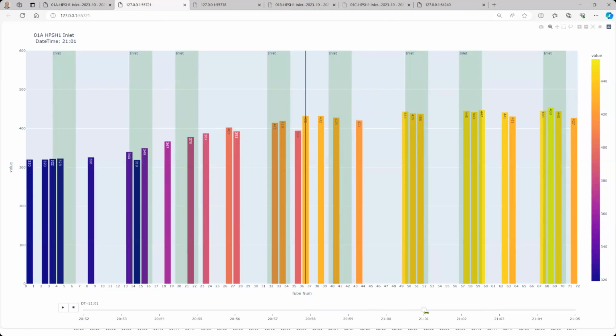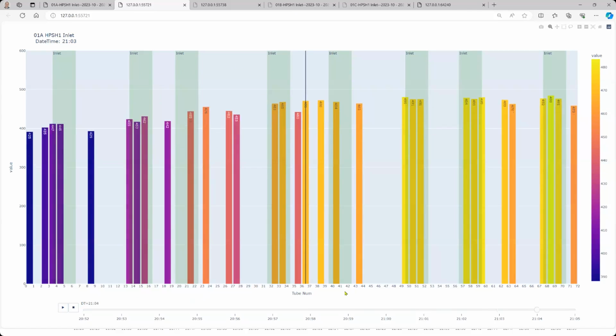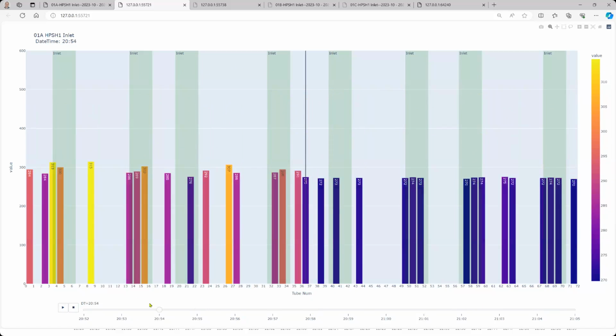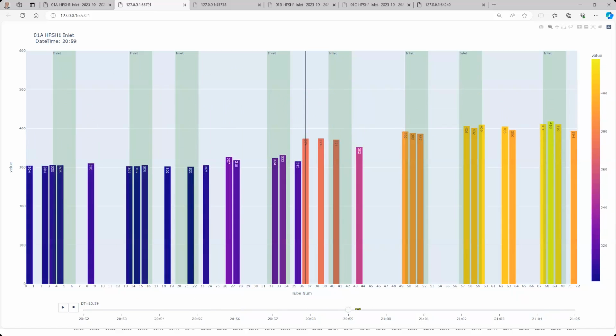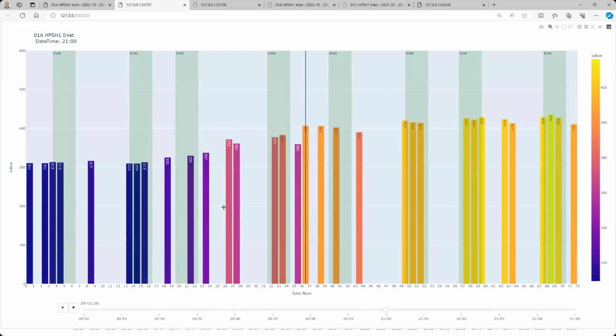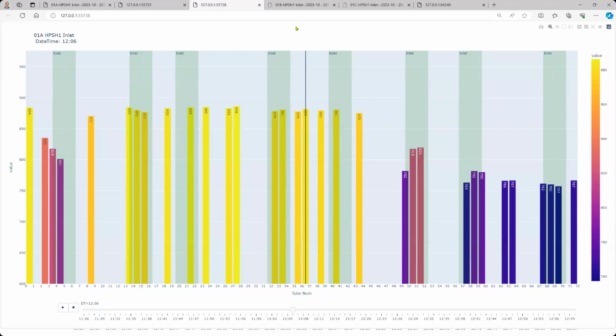If I zoom in here just to around this time, I can plot this versus time showing what happens to a bunch of these, but what I was trying to get to is that the temperature differential is really that the tubes on one header are getting cooled more than the other. But if we're looking at tube to tube immediate differences, which is going to drive fatigue damage on these local tube to header welds, those are not as high. So this is, for example, one of the differentials that we're looking at in calculating damage in our models. But there's a bunch more that we could go through, given more time.